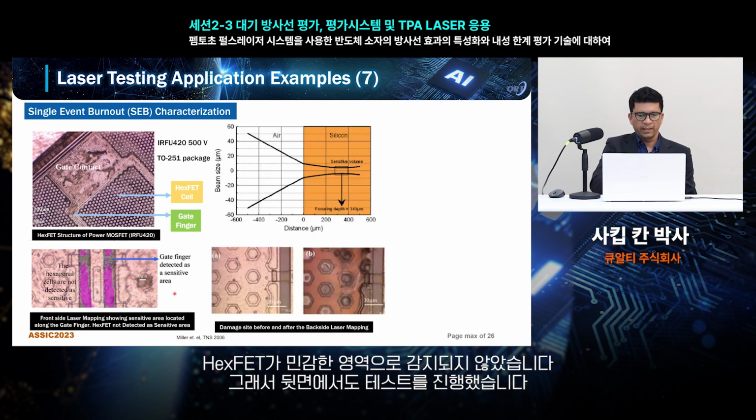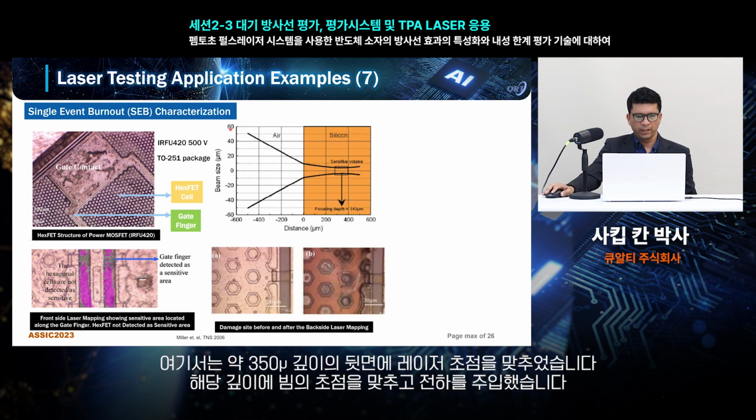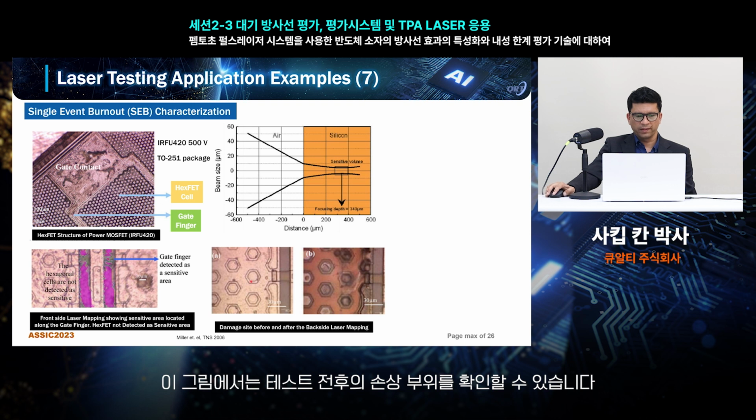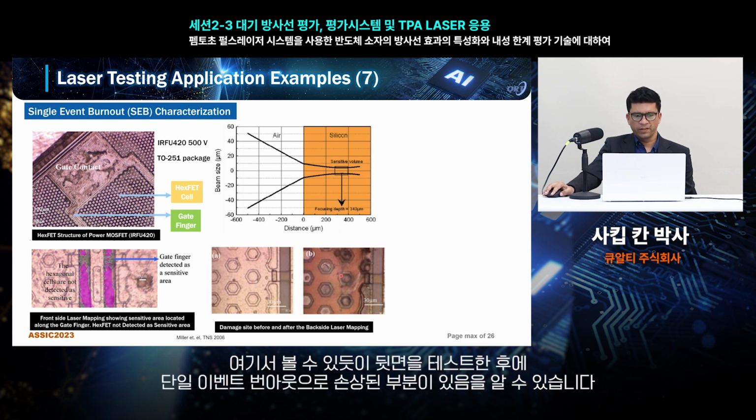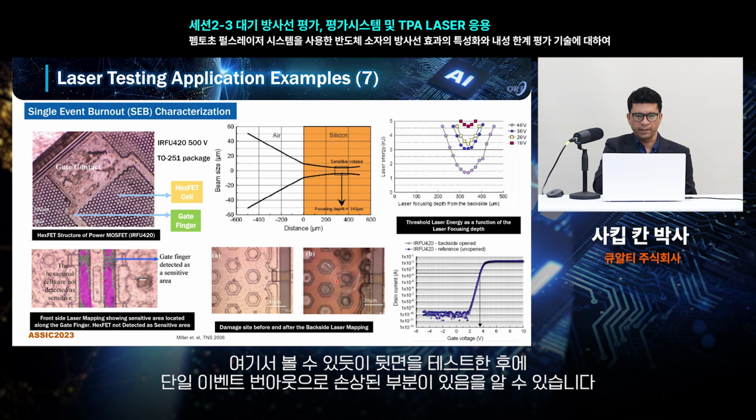So the backside testing was also performed. Here you can see the laser is focused from the backside at a depth of around 350 micrometers. The beam was focused at this depth, and the charges were injected at this depth. And this figure shows the damage site before the testing and after the testing, and you can see the damage site of the single event burnout after the backside testing.